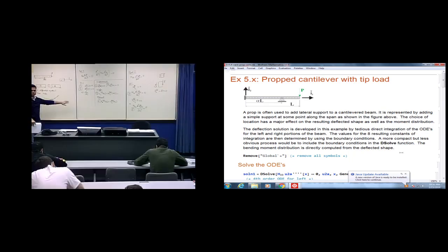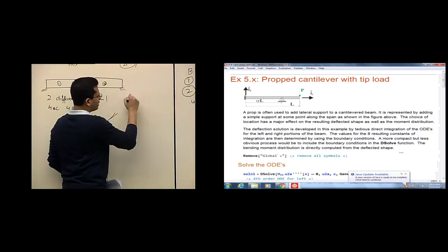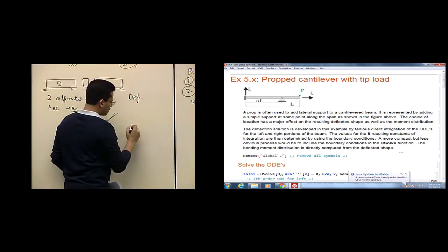We do not need to go to shear force. And why is that? Because we are already defining displacement 0. Displacement 0 causes shear force to take a particular value, and that's the reaction force, right? So when you have a cause in the problem, you cannot have the effect on the same boundary. If you are imposing conditions on displacement, you cannot have conditions on shear force.